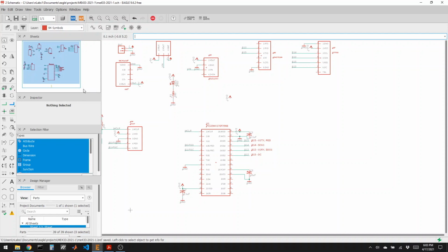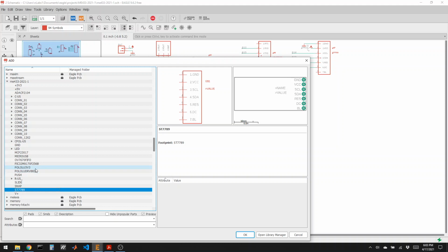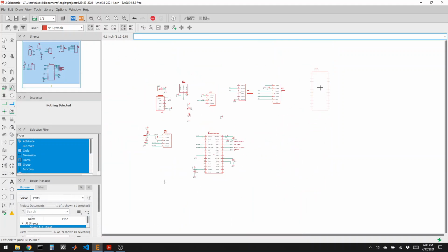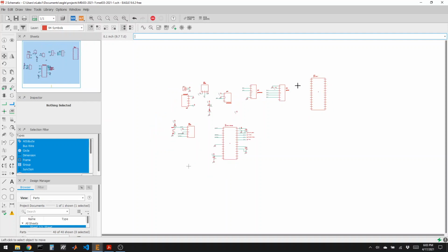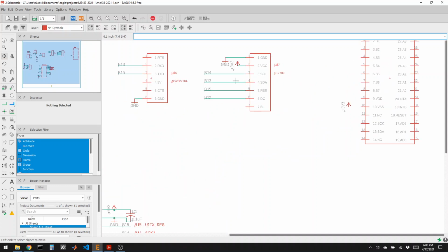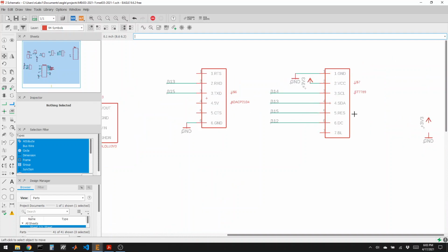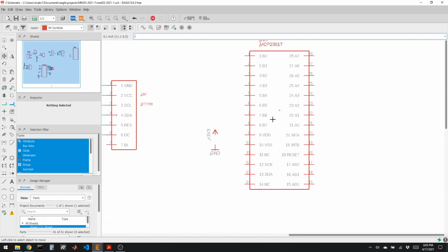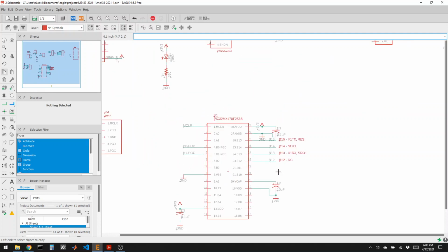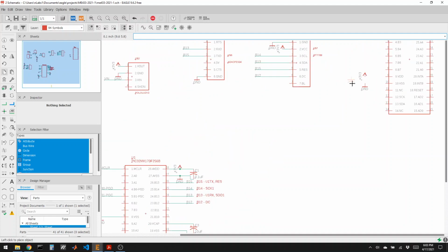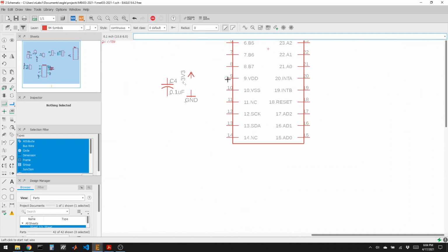Now we're going to need more pins. We'll save the camera for last. So let's connect the I/O fanning chip, the MCP23017. It has 1 power and 1 ground. And then typically wherever something has a power and ground connected to it, you should add a capacitor, a 0.1 microfarad capacitor. These boards, the little adapter boards that we've pre-bought, they usually have the capacitors online. This kind of DIP chip doesn't have that built in, so let's be sure to at least give ourselves a spot to solder one in. We don't necessarily have to. They call these a bypass capacitor. Power 3, ground, 0.1 microfarad capacitor.